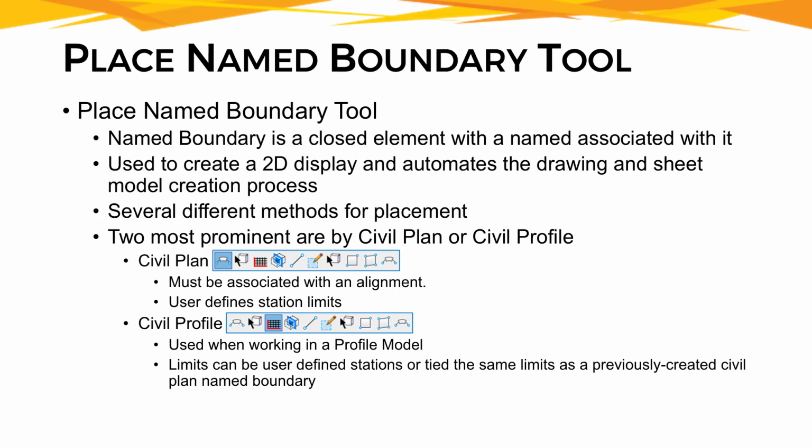The civil profile placement option is used when working in the profile model. Again, there are several different options and toggles that we'll demonstrate in the actual exercise, but one of the important things to note is that the limits can be either user-defined, similar to the plan view, or we can link the limits directly to the existing plan view limits.